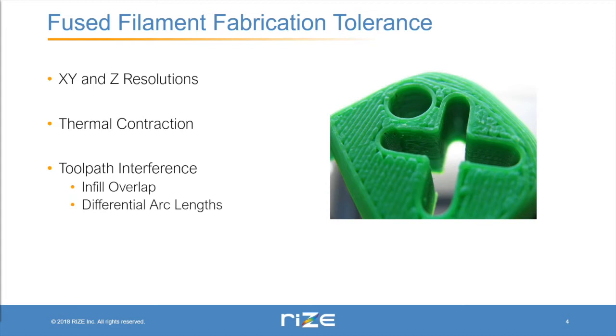As a part is being printed, the thermoplastic is being heated up very hot to the point of melting or nearly melting, and after it's been placed, it starts to cool down, and depending on the rate at which the material cools down relative to the material that's already on the build or is being applied to it currently, this can create some internal stresses in the part that could eventually pull up at the corners of the part or cause some changes in the geometry.